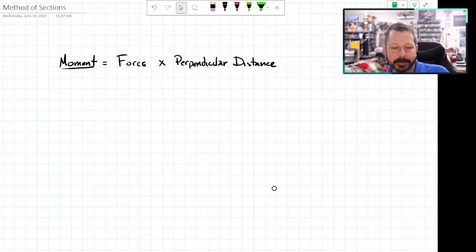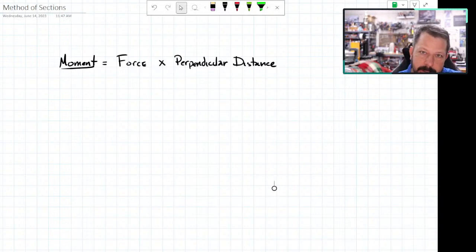It doesn't have to be in every case; you can do vector math with a force vector and a distance vector and calculate a moment. But we're doing everything in rectangular components, x and y, so it's much simpler if I'm looking for a force creating this moment effect about some remote point, and I need the perpendicular distance between that force and the point I'm interested in.